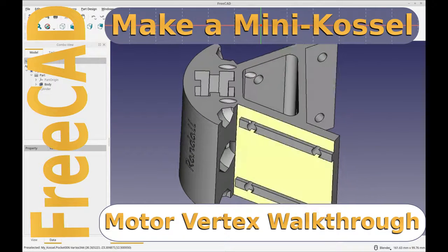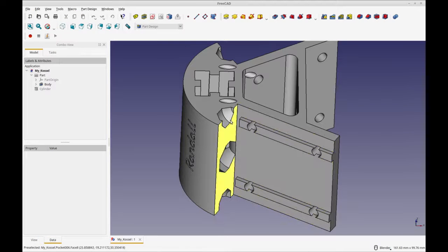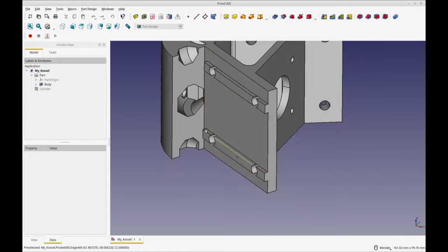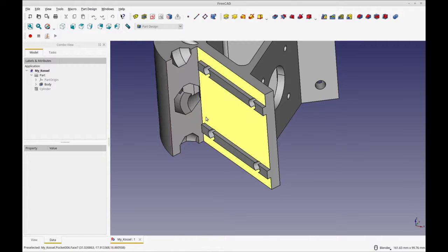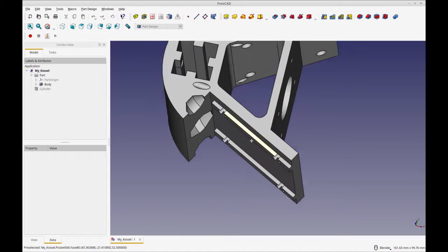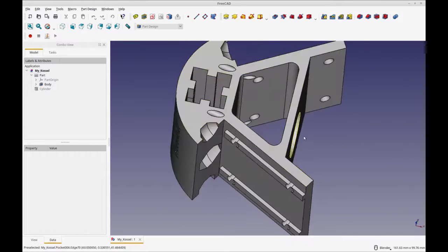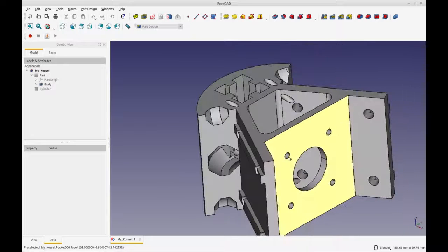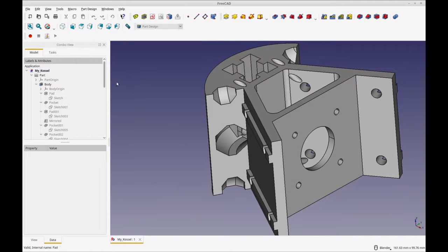And some of the other exceptions are I did a sweep here. Other models have two sort of pocket things, and frankly I just found them too cumbersome to do. I also did a sweep here, and similarly they had two pockets, or two separate geometries moved, and it seemed overly complicated for FreeCAD. Maybe it's easier in others. You can see, for some reason it didn't mirror over here, but that might just be what I have selected.